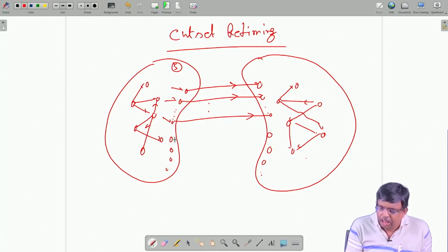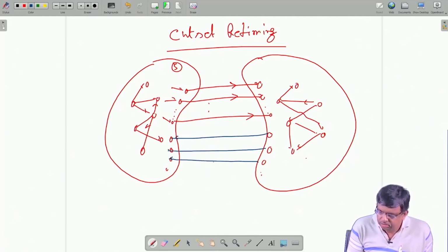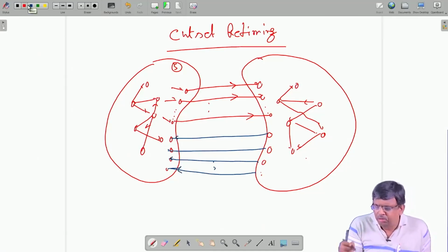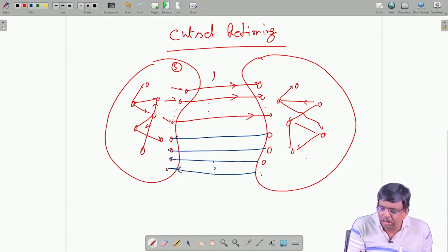And from some nodes here there will be edges on the reverse side. They may have delays, may not have delays. So, I just remain general. I say that it may have a delay L1 times D, it may have L2 D, and so on, maybe total I have got LP. So, a total of P edges in this direction, with L1 to LP delays. All these delays are non-negative, they cannot be negative, either 0 or positive.